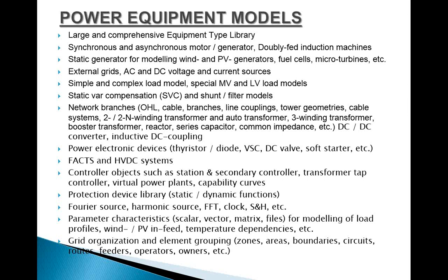Short circuit calculations can also be done on wind generators, with optional inclusion of dynamic voltage support according to K factor settings. Power quality assessment according to IEC standards can also be done on wind and PV systems. Stability and EMT analysis can also be done. Wind turbine models for different generator and converter types can be done.